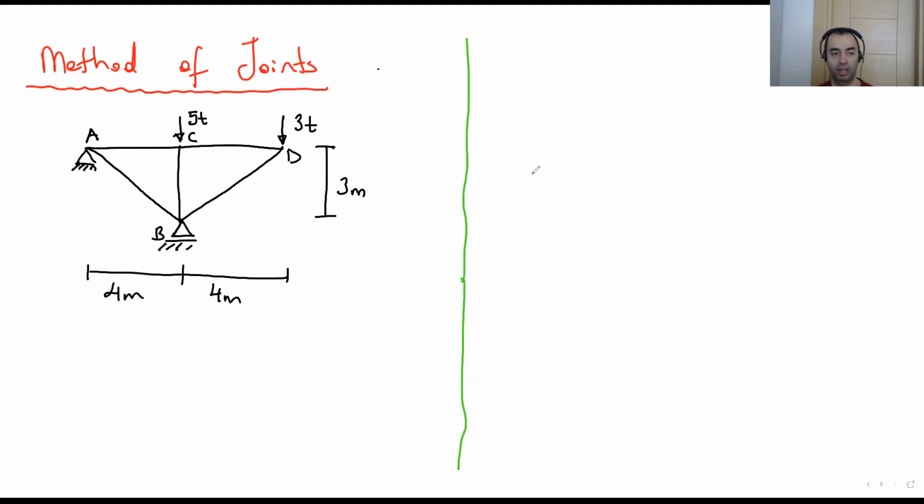After we calculate all these support reactions, then we can go to the member force calculations. Here we have a pin support. You can see here vertical A. Also, we have a horizontal A here. Here, this is roller support. There's spacing between the triangle and this line. So this is vertical B. Let's calculate the support reactions here.